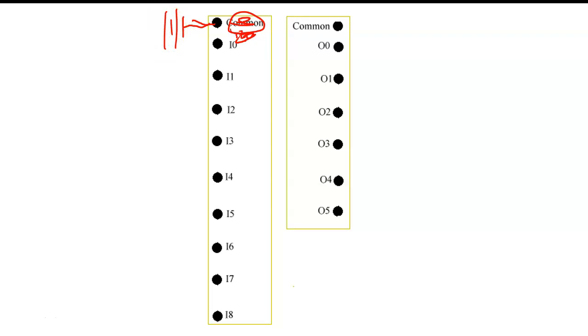If you took your meter and went from the common down to plus, it would measure 24 volts with the plus on the red. Then the way our PLC hooks up, everything we hook up hooks up here, whether we're doing a push button or a sensor or limit switches or whatever. You're going to have to mark this out, and over here it's got common coming out of the port. But the common, we're running sourcing output.